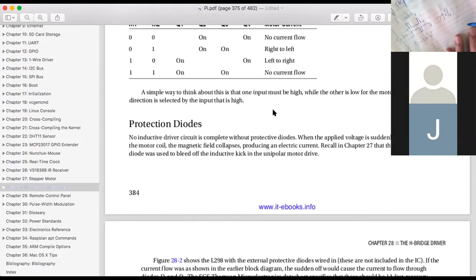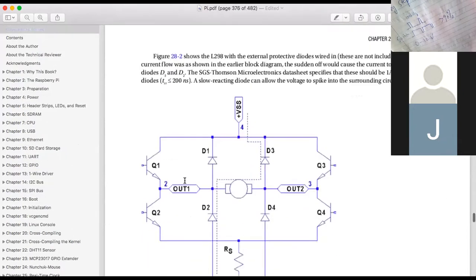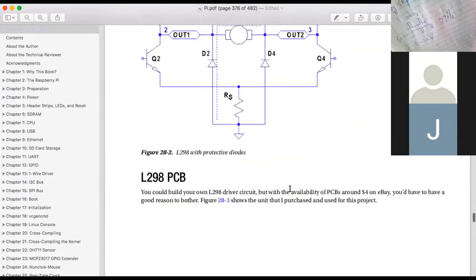That means for every 9 watts going to the motor, there's only 1 watt wasted on the electrical drives. So the electrical drives will be relatively cool compared with the other drives, which will be very hot. So switching drive is all about efficiency. So we are turning this thing on and off using PWM.